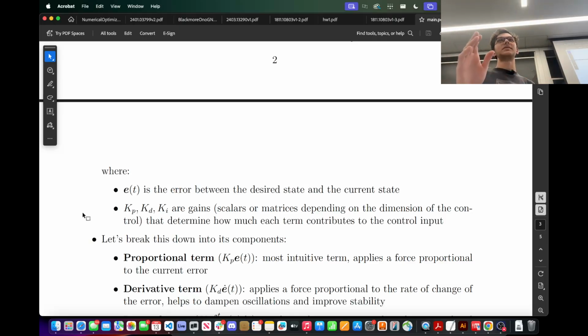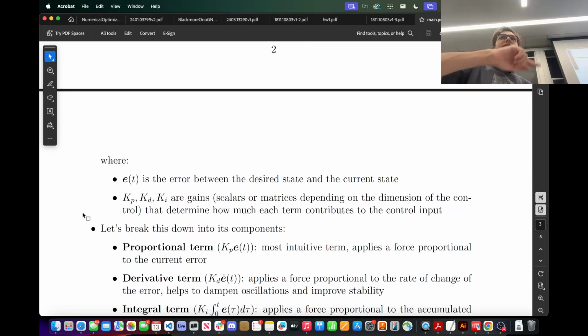With no damping, you'll almost always have oscillation in the reference tracking. By reference tracking I mean I have a reference, i.e. where I want to be, and tracking is getting to that reference by applying some control law. The derivative term helps dampen things out.